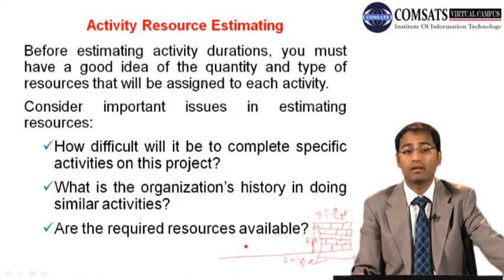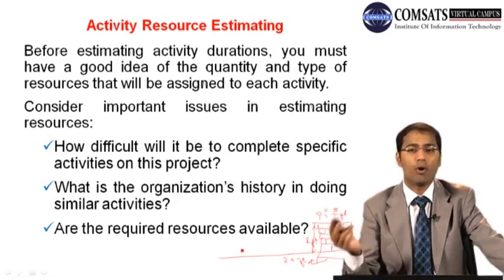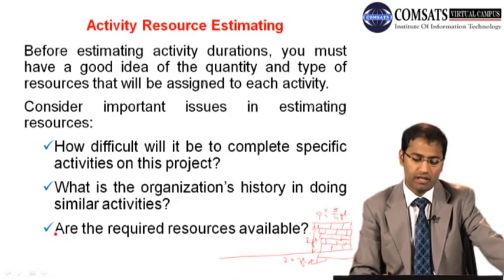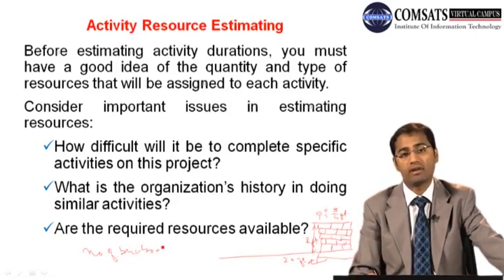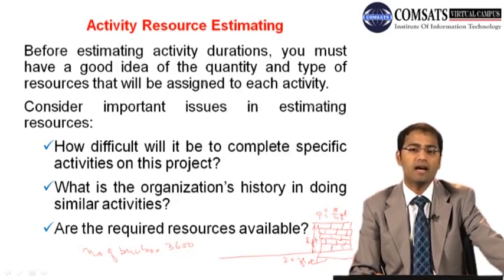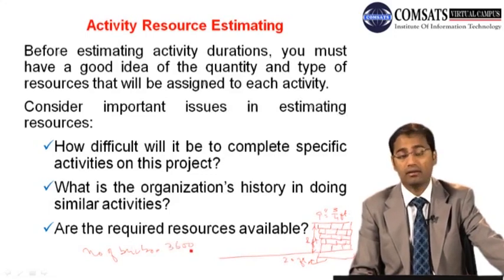But the quantity is in cubic meters. Now we have empirical relationships between the volumes and the number of bricks. In this fashion, we can calculate how many bricks we need. So through this procedure, let's say we have calculated 3600 bricks. Besides constructing this brick masonry wall, we are in need of bricks, but again we are also in need of mortar for binding, you know.